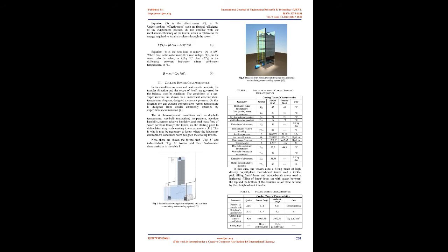Although appropriate selection of the cooling tower size establishes the equilibrium temperatures at which the tower will reject a given heat load, the actual heat load itself is determined by the process being served. Everything else being equal, the size and cost of a cooling tower is proportional to the heat load. Therefore, it is of primary importance that a reasonably accurate heat load determination be made in all cases. If the heat load calculations are low, the cooling tower purchased will probably be too small. If the calculations are high, oversized, more costly equipment will result.